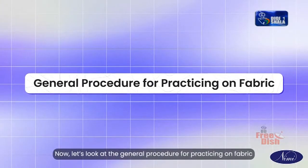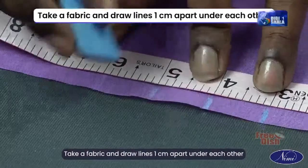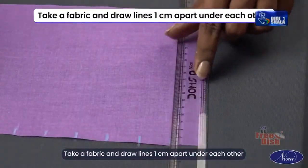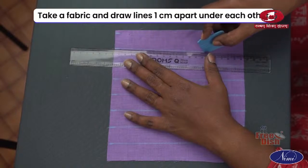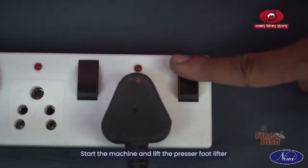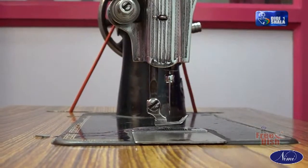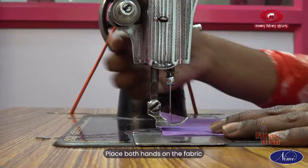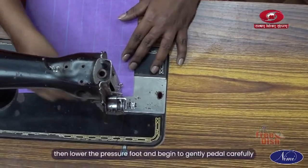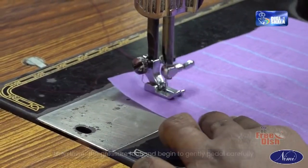Now, let's look at the general procedure for practicing on fabric. Take a fabric and draw lines 1 centimeter apart under each other. Start the machine and lift the presser foot lifter and place the fabric under it. Place both hands on the fabric. Then lower the presser foot and begin to gently pedal carefully.